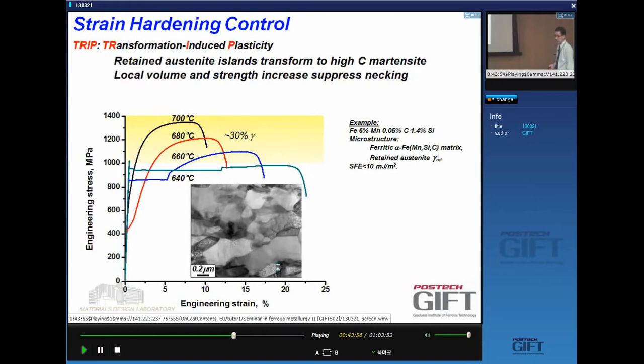So we have an interesting material that has a TRIP effect. So some of this microstructure, about half of these grains, are austenite, yes? But it's an ultrafine microstructure. And I started my presentation by telling you ultrafine microstructures are bad, right? And it turns out that indeed, if you don't doctor this type of medium manganese TRIP steels, you do not get good properties. Like, have a look at these properties here. So if you look very quickly, you say, well, I get 20% and I get strengths above 1000.